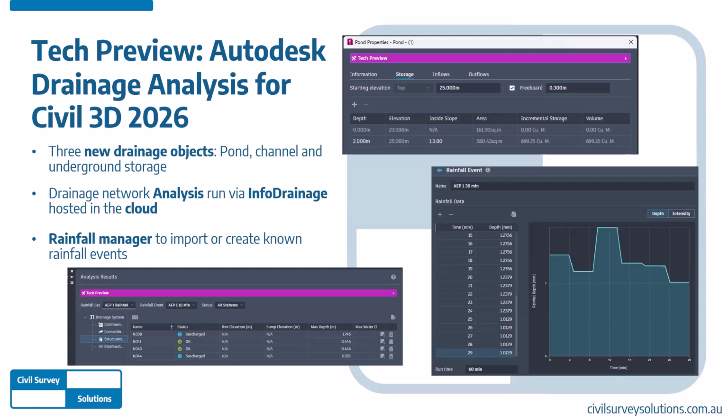The way that this tech preview works is that you're able to run drainage analyses via InfraWorks, so using the InfoDrainage analysis engine, but those calculations are all hosted in the cloud. And what that means is that you can run these analyses without having to leave Civil 3D. There are 3 cloud servers to choose from at the moment. It is only available in certain regions, and those are one located in the USA, one in the United Kingdom, and one in Australia.